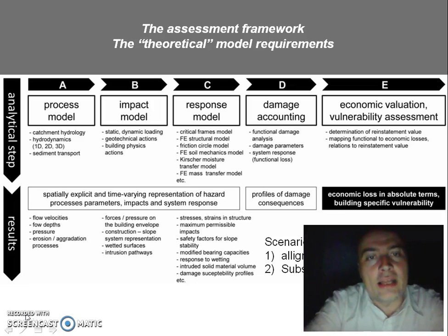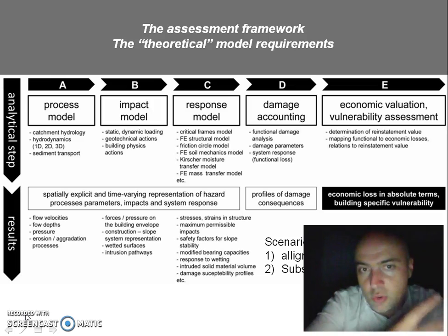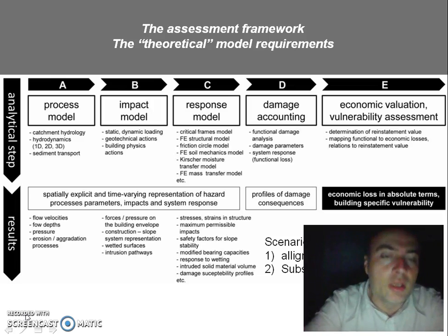We can start calculating the impact on the exposed structures in terms of static and dynamic loadings, geotechnical actions. Just imagine that channel incision might destabilize from a geotechnical perspective a building, even without interacting with the building directly, because the geotechnical mechanisms could be due to a loss of bearing capacity of the soil, for example.